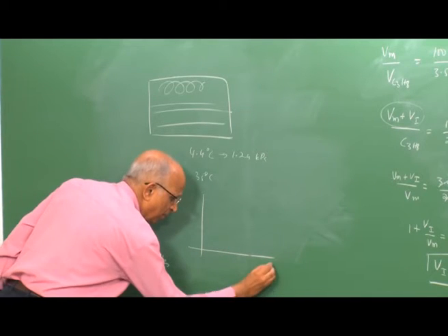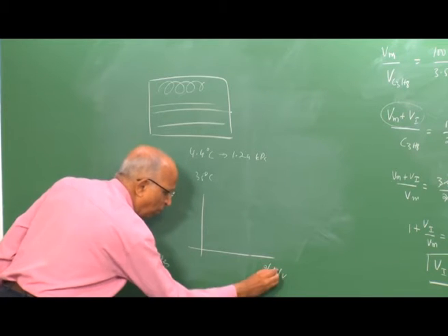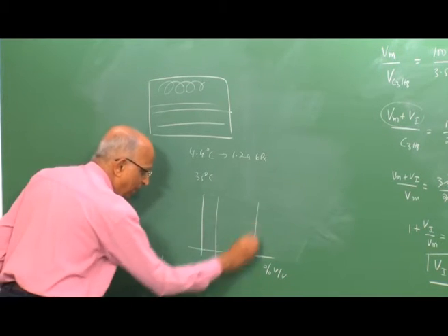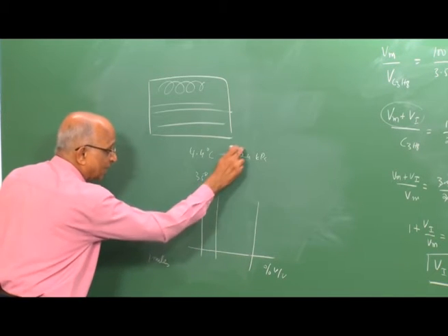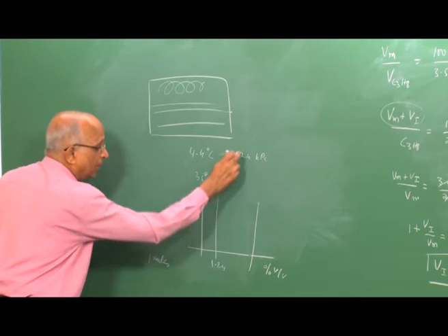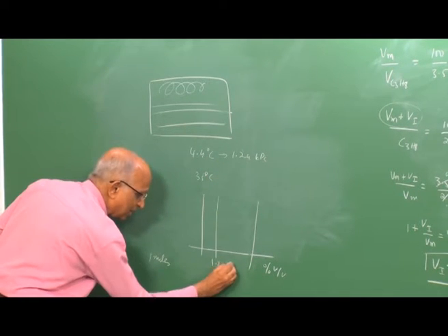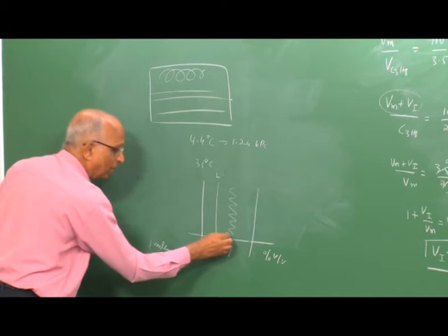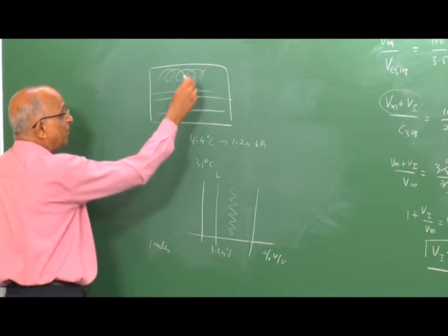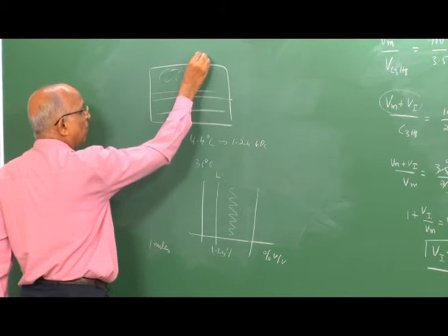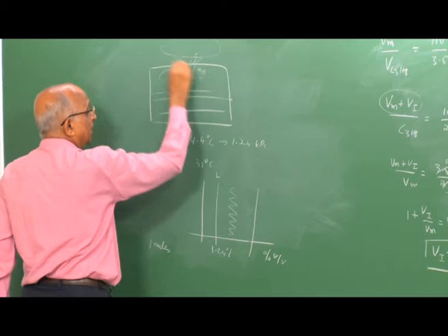In other words, if I plot percentage volume by volume, volume toluene divided by volume of the mixture, maybe these are the limits of flammability. The limit as calculated from this comes to be 1.24 divided by 100 times 100. This is the percentage, this corresponds to L. Maybe our mixture is somewhere here, highly flammable. Since a highly flammable mixture is getting generated, maybe there is some leak over here, and it forms in the cargo bay.